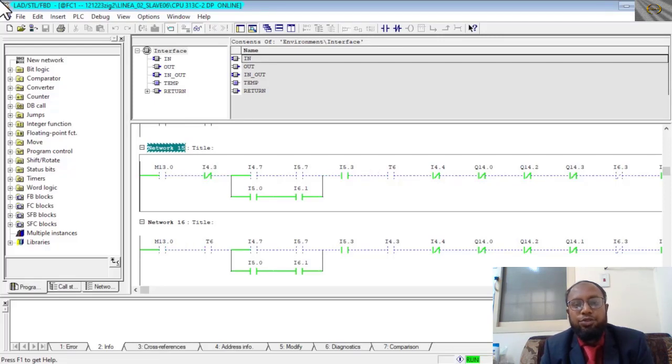Now we are trying to run our machine, but there is some issue with T6. T6 is not running, not on. For this reason we see the jig operation is not working properly. High speed mode is on. Our jig has two conditions: one is fast forward and one is slow forward. Normally we run our machine slow forward. But here T6 is normally stopped, so it works in fast mode, running faster. For this reason our problem is not solved yet.